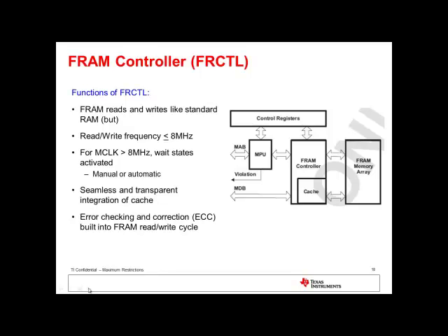On the FR57xx device, this write-back is implemented inside the FRAM IP automatically and in the background, requiring no user interaction. The FRAM controller also has a built-in error correction code, ECC, logic that is capable of detecting and correcting bit errors. There are three options for programming an MSP430 FRAM device. They are programming via JTAG or the SPI-by-wire interface using the MSP430 FET UIF, programming via the ROM BSL, and programming via a custom solution.